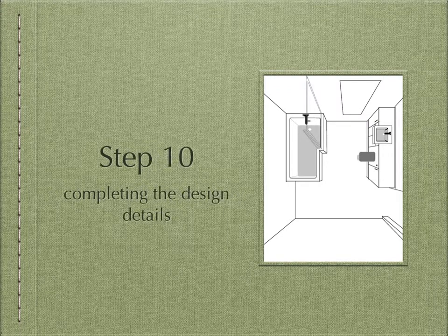And now we're trying to depict the shower screen. The bath is a shower bath, has a shower screen, and generally speaking, rather than try to produce a firm defined shower screen, we're going to do a ghosted screen. So you can just see the outline of the screen. It doesn't take over the drawing, it shows that it's there, and you can put a bit of shading on it. You can do quite a few bits to enhance it, mostly in fact with colour really, but that is all you need, and I find it works extremely well.